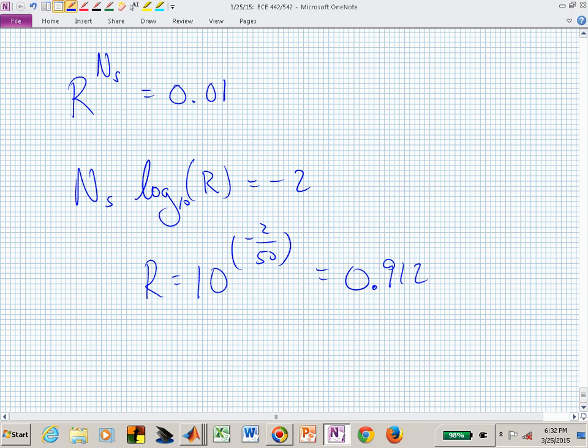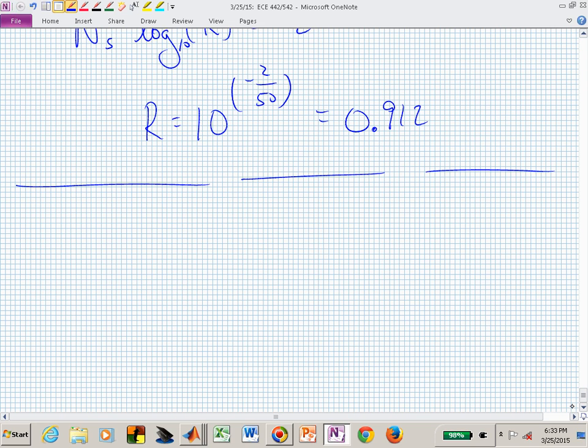If somebody now gives you a sample or a settling time of 50 samples, you now know you're a little bit beyond 0.9 or 90% of the way towards the unit circle. So that's not that far in, but a lot of stuff happens around 1 and a little bit interior to 1. If we now had dominant poles with a radius of 0.912, that would satisfy our settling time spec of half of a second for this sampling period.